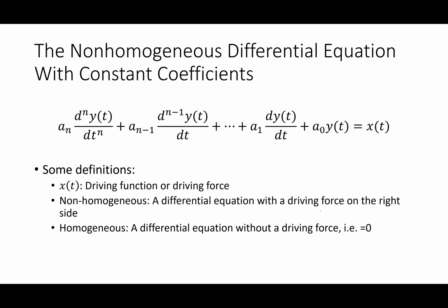So in general, our differential equations are always going to look like this guy, non-homogeneous, and they're always going to have constant coefficients. In other words, the things in front of the derivatives are always going to be constants. They're not going to be functions of time. Those from a circuit come from resistors, capacitors, inductors, whatever. On this side over here, the side without the derivatives is always going to be a driving force, some input to the system.